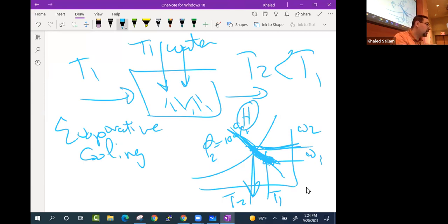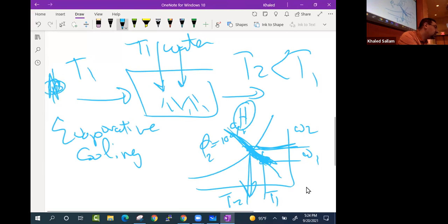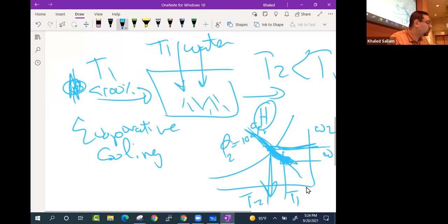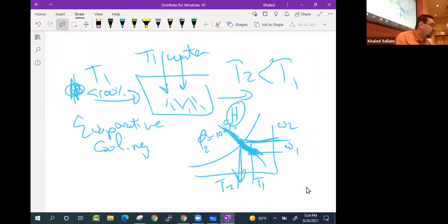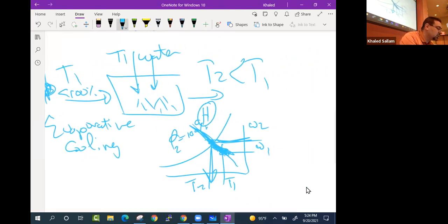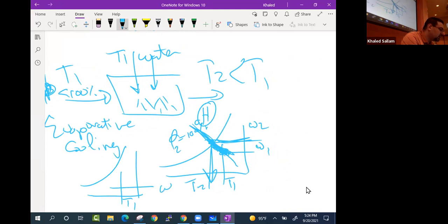And so although the total H is constant along that line, you are cooling the air, right? And so you can do this especially in desert or arid conditions when phi is less than 100%. Hopefully if it's dry heat, then the humidity will be less than 100%. And the lesser it is, the better, because imagine if, yes, T1 is hot, but W1 is really small.